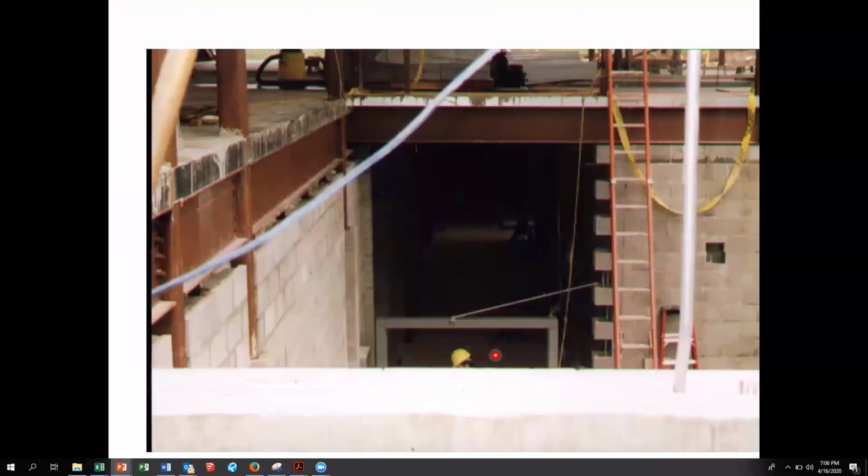Now what they did here, here's what's known as the door frame. Sometimes they call it a door buck. And this little piece right here is a telescoping brace. So they're bracing to the wall. But they wanted to get this wall done. They must not have had the door frame on site. So they did what's known as a sawtooth pattern so that they could get most of the wall in here. Then once the door comes in, they finish off the rest of that opening.